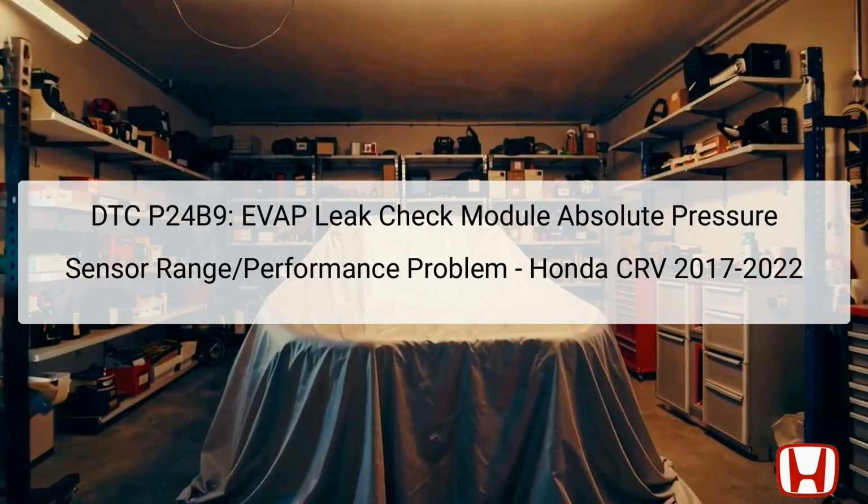The DTC P24B9 indicates a malfunction in the EVAP, Evaporative Emission Control Leak Check Module's absolute pressure sensor. This condition suggests that the voltage signal generated by the sensor is either out of range or not performing as expected. The EVAP system's primary responsibility is to capture fuel vapors from the gas tank and prevent them from escaping into the atmosphere, thus minimizing environmental impact.